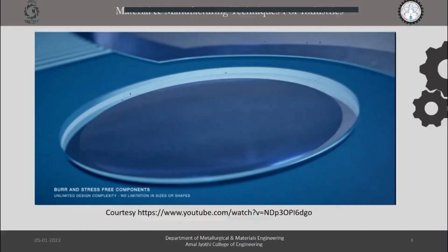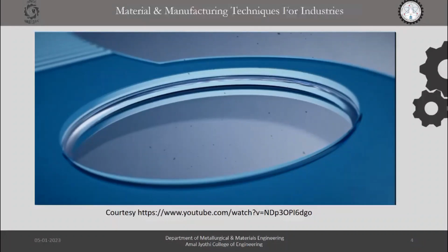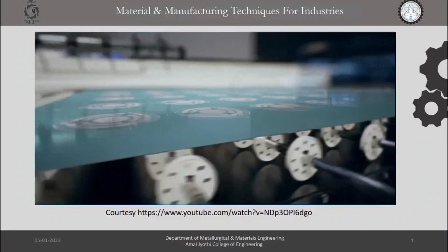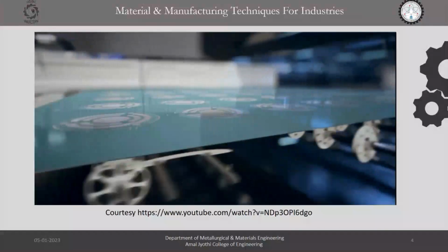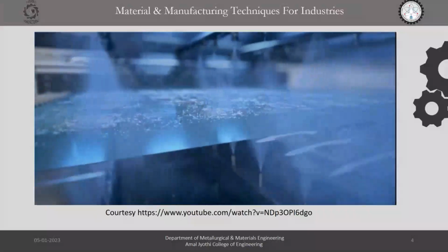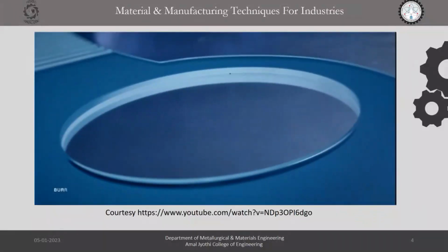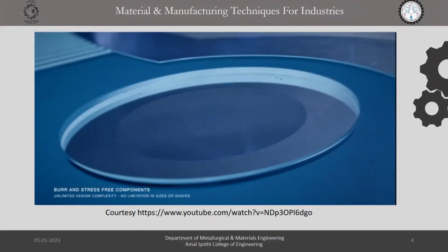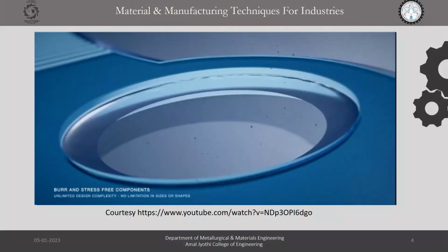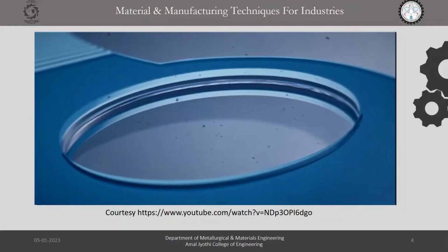In order to obtain this desired structure, a coating which is non-reactive to the chemical reagent is applied. This coating is known as maskant. The maskant is applied in a desired shape, and we dip the workpiece into the chemical agent in order to remove the unwanted area.